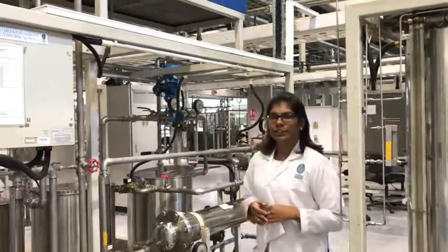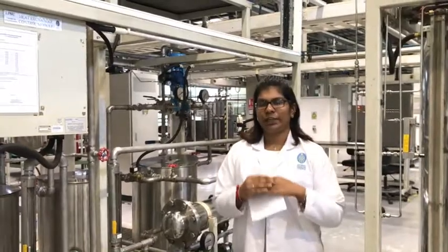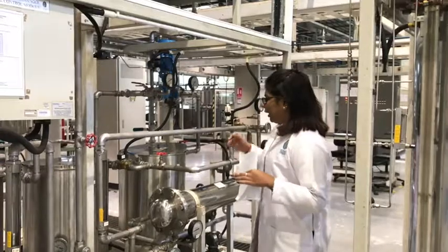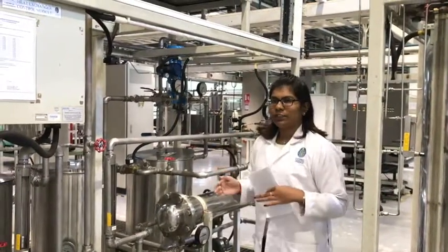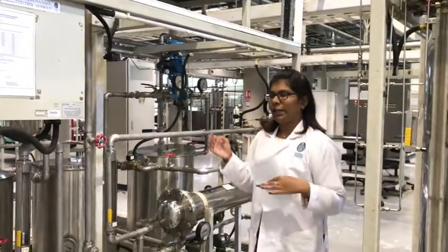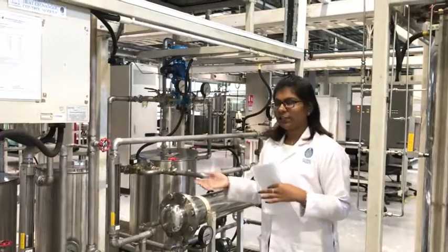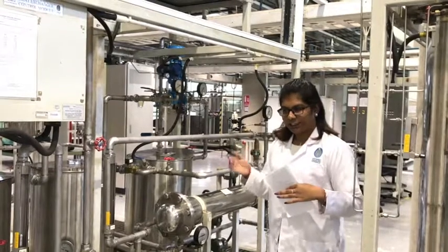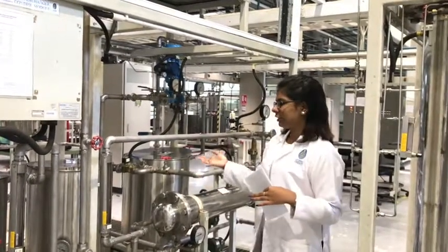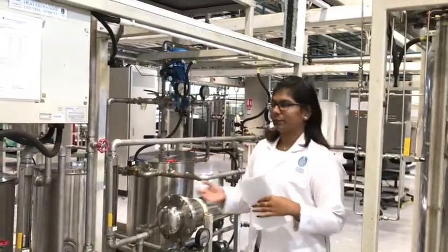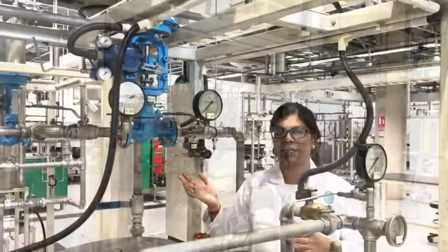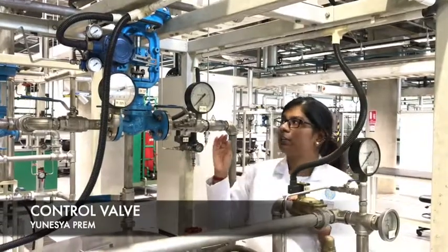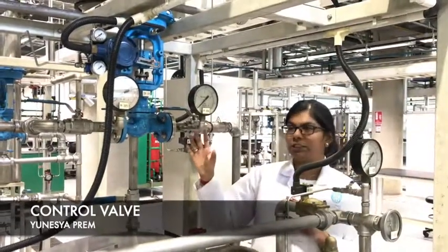The heat exchanger used in this experiment is a shell and tube heat exchanger with one shell and two tube passes. In the heat exchanger, the hot water is circulated in the tube side and the hot water returns to the hot water tank. The cold water is circulated in the shell side and the product is collected in the product tank. The purpose of this experiment is to control the flow rate of the hot water. So a control valve is used to do this.